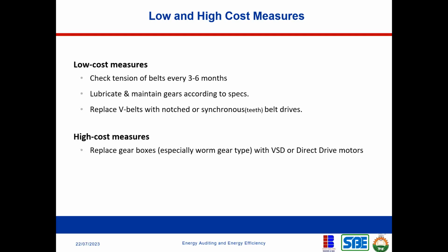And these are measures you can take to lower the cost of your drive. So for example, if you don't have the right kind of drive, you might need to change your belt. If your belt is not proper, you might need to frequently change your belt, or your drive might induce slip into your motor system. Drives can introduce slip into your motor system. So you need to make sure that you use the proper kind of drive. So these are low and high cost measures for drive system.